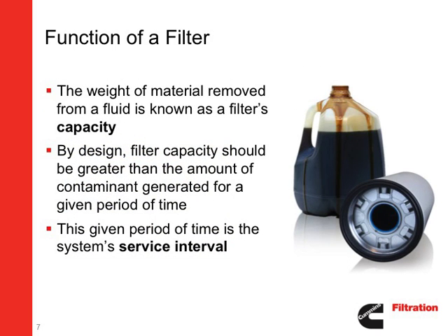The weight of the maximum amount of material removed from a fluid and held by the filter is known as the filter's capacity. Filters have the capacity to hold a certain amount of material, and that capacity is designed to be greater than the amount of contaminant generated for a specific period of time. This given period of time is the system's service interval, or simply put, the time between filter changes.